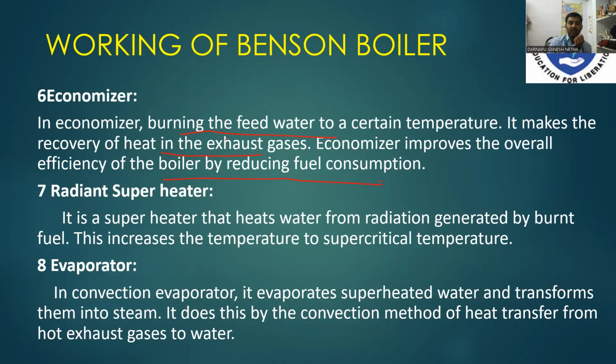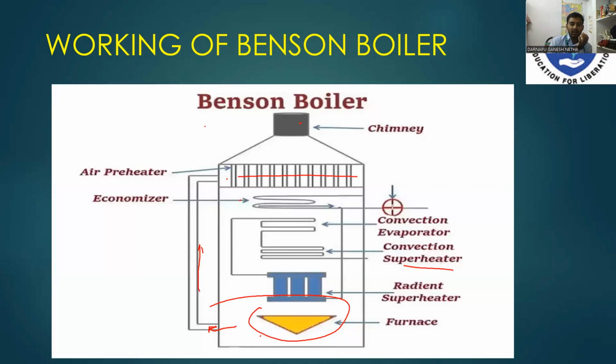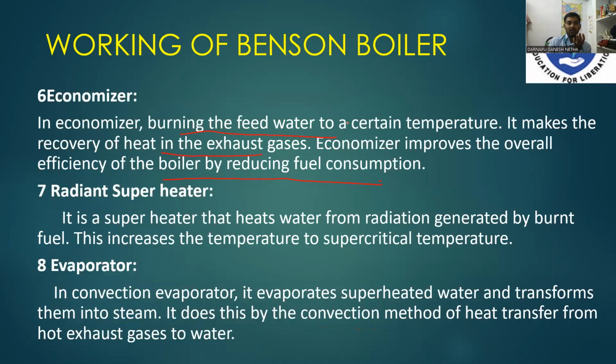What is the function of the economizer? Here the feed water, this is the economizer. In this economizer, the feed water which is sent by the pump is heated up to a certain temperature, and also reduces the fuel consumption. Indirectly, the economizer reduces the consumption of fuel by heating the feed water.